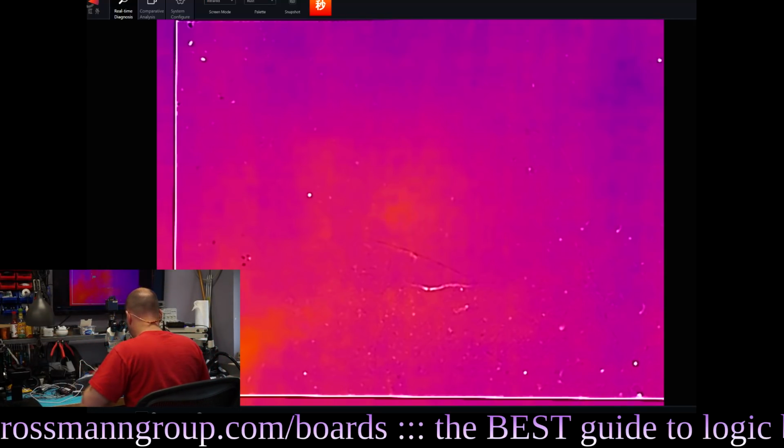First thing, let's get this off of here and see if it clears the short. That went to 130 Celsius in under 2 seconds. Yes, it did. Have you ever seen a short that hot in a MacBook before? No. Not that quick either. On a MacBook, the boards have all that heat dissipating capability, huge absorption capability, ground plane. On these boards, they're really small, and they probably don't have that. So if a chip has a short, it just burns right through everything.